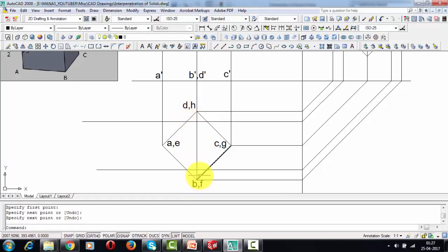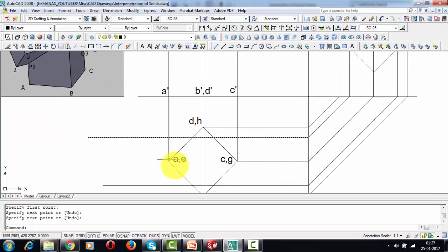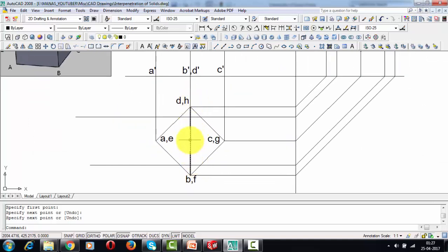Now, the horizontal prism that we do have here is having an axis length of 100 millimeters. So I've taken this mid line, and towards the right we're going to draw a 50 millimeter long line. Towards its left we're going to again draw a 50 millimeter long line, so that the overall length works out as 100 millimeters. So let's do that. I'm going to start from here.